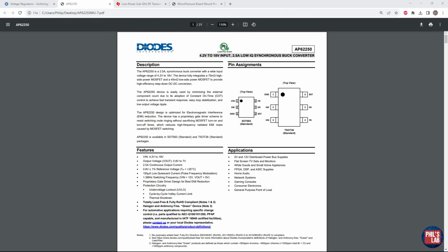Datasheets will tell you about ratings, timings, bus specifications, seeing what external components you might need to interface this with the rest of your hardware design. Datasheets will tell you about mechanical aspects and are also helpful for firmware in certain cases, for example, telling you about register maps, which will help you write drivers and so on.